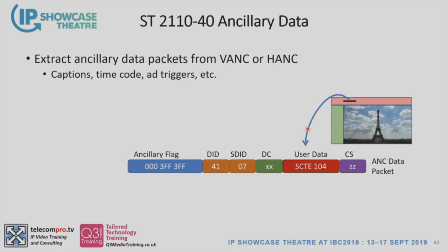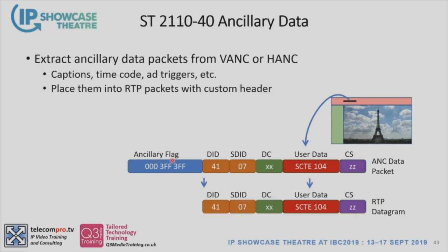You take those ancillary data packets, you get rid of the header that was required in SDI, but you keep all the rest of it. So you keep the data identifier, the secondary data identifier, the data count, the user data, the checksum, all of that information that comes to you natively in SDI remains exactly the same when we convert it over for 2110-40.